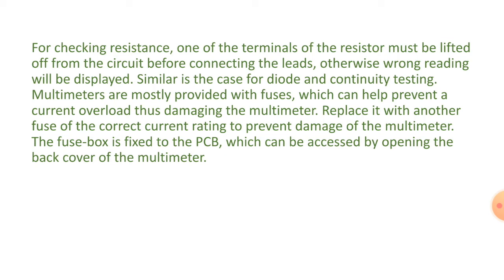Multimeters are mostly provided with fuses which can help prevent a current overload, thus damaging the multimeter. Replace it with another fuse of the correct current rating to prevent damage of the multimeter. The fuse box is fixed to the PCB, which can be accessed by opening the back cover of the multimeter.